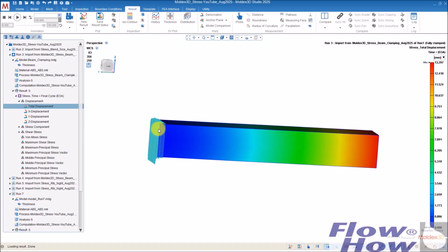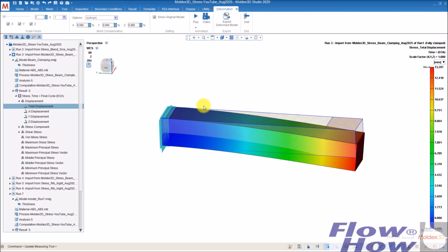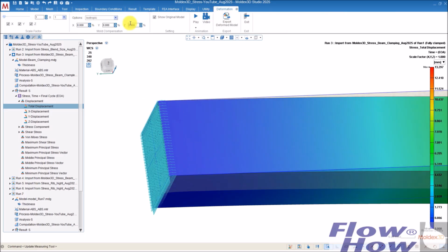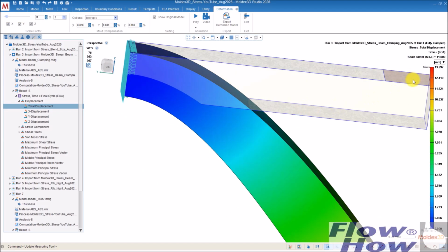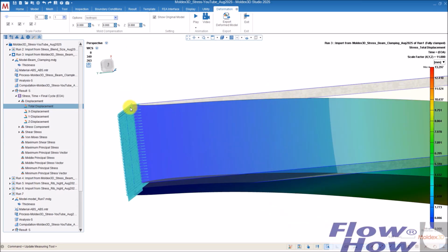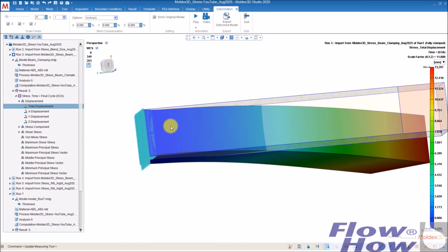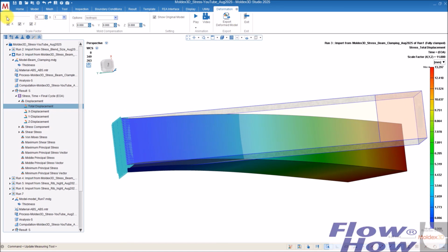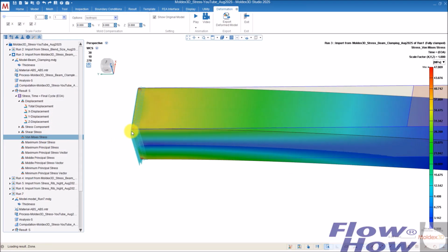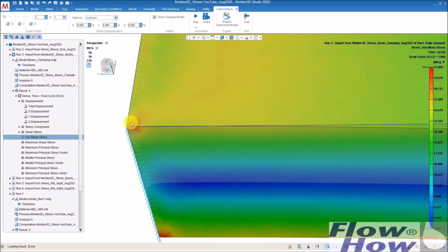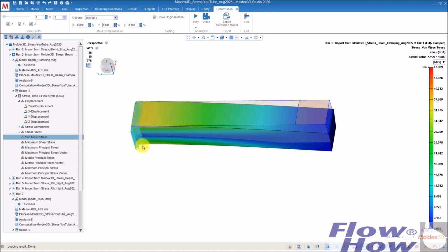This one I have clamped X, Y, Z in all directions. So if I look at the deformation, you can see, I'll try to scale it, and it's a big deformation, 13 millimeters, and you can see it's clamped here, so you get some unnatural movement there. So if I look at the stresses, you can see I introduced some not real stresses maybe in that area. Or maybe I have these stresses, I don't know.